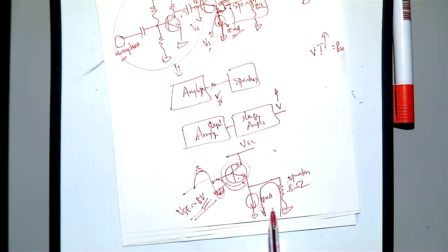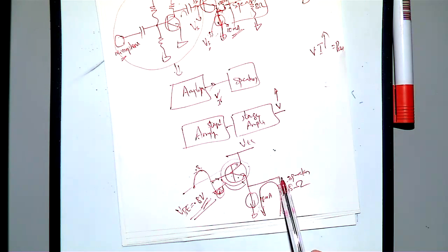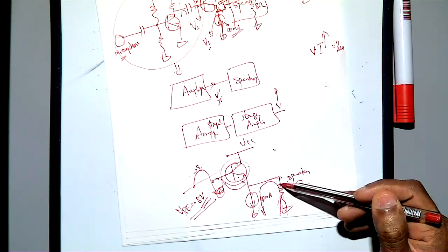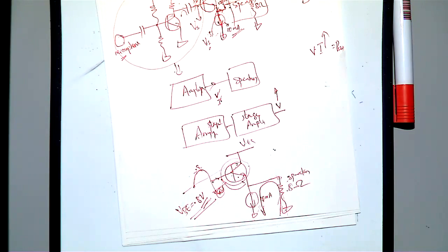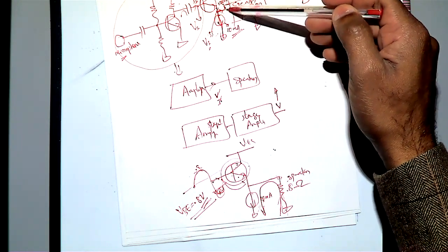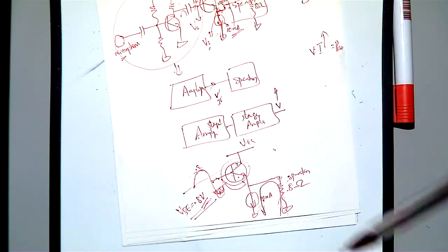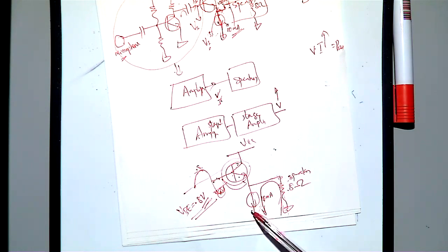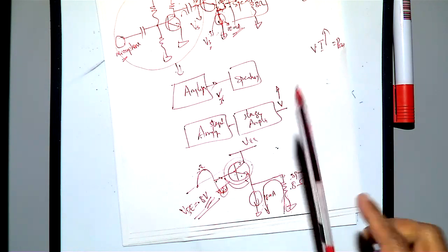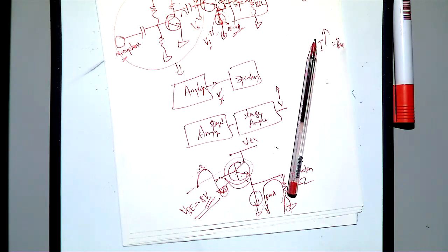So this current source will draw current from here, so you will see a small negative voltage here, because the current direction is from ground to here. So when you are designing, this is not, I wouldn't say, a proper power amplifier. Maybe you can say yes, the emitter follower is a power amplifier, but this one has an issue as a current amplifier. This issue is a problem. Then what can we do? So that's the beginning.